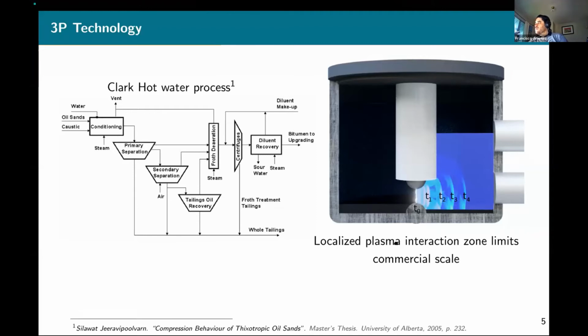The premise of the technique is straightforward, and you can see in this figure how it works. We have two electrodes with the slurry mixture in the chamber, and we shoot the discharge and generate shock waves, and those shock waves promote physical and chemical reactions in the slurry that promote material separation. Here you can see the simulated shock wave at 3 different times, where T0 is basically when the discharge appears, and then at different times how the shock wave moves in the reactor.